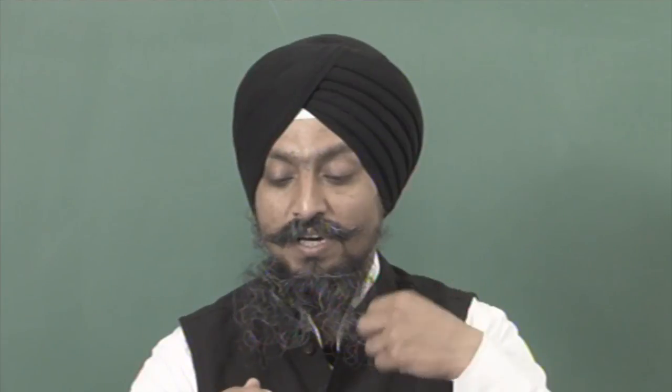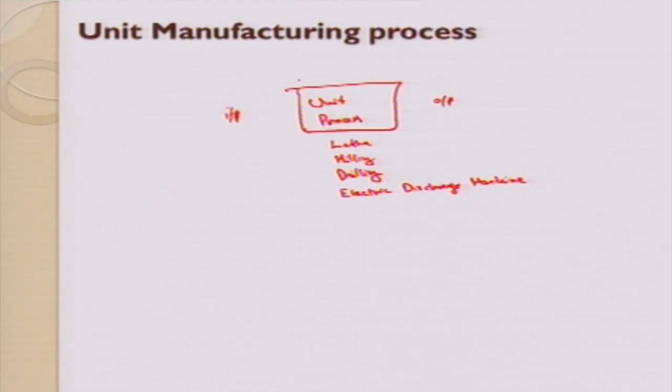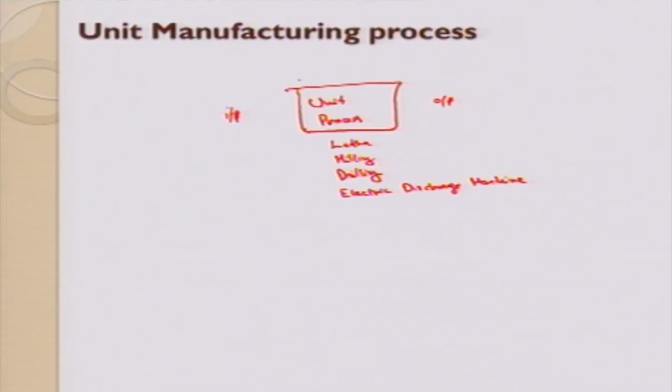And I would say then second point is energy waste. Waste is, for instance, the cutting fluid that is used. We can think of replacing cutting fluid with some biodegradable fluid. We can think of minimizing the use of cutting fluid and all those things. So these would be the responses, the energy, waste. Input parameters would be feed, speed, depth of cut. Responses may be the pollution, waste produced, like I just said. And energy and the quality.